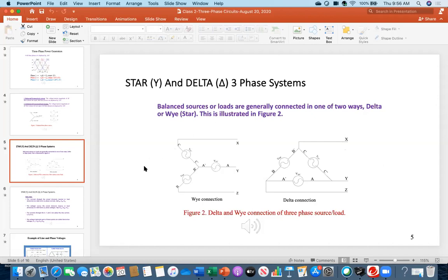Yes. So just keep in mind, in real life, for example, when you are going a long way, driving on the highway, you might see several cables. Typically, you might see 8 cables. Those are typically the Y connection, the three-phase and neutral line. So this means 1, 2, 3, and then neutral, 4 cables, and there should be another 4 cables, another Y connection. That is just for reliability purposes.